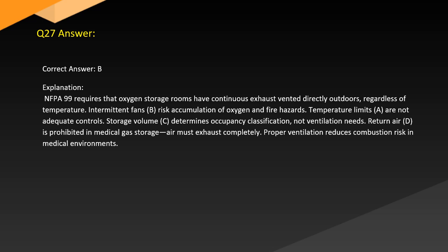Temperature limits (A) are not adequate controls. Storage volume (C) determines occupancy classification, not ventilation needs. Return air (D) is prohibited in medical gas storage. Air must exhaust completely. Proper ventilation reduces combustion risk in medical environments.